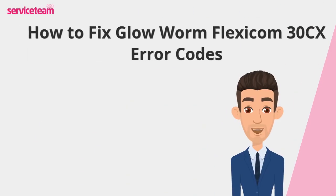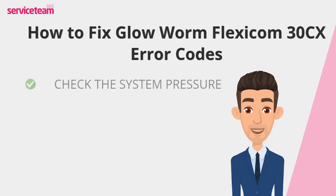Let's find out how to fix the Glow-worm Flexicom 30CX error codes. Start by looking at the pressure gauge. When the system is cold, it should sit between 1.0 and 1.5 bar. If the pressure is low, use the filling loop, the small silver braided hose underneath the boiler. Gently open both valves and watch the gauge rise. Once it reaches about 1.2 bar, close the valves again and reset the boiler.